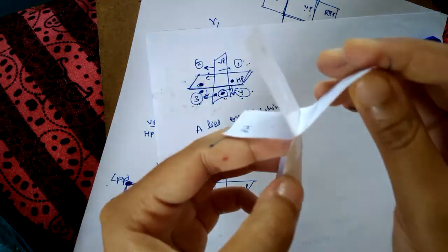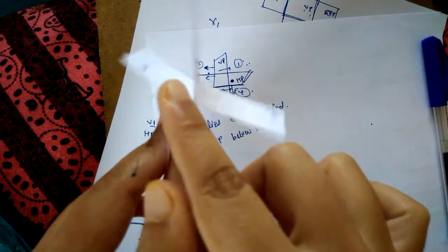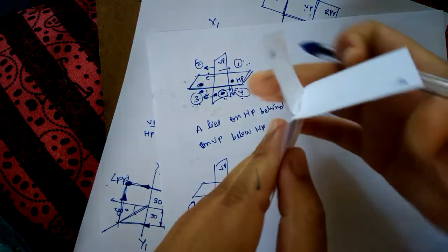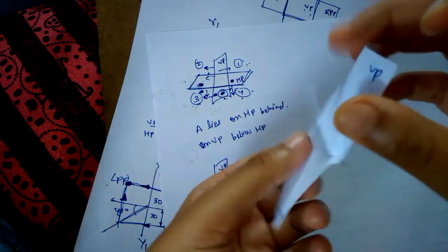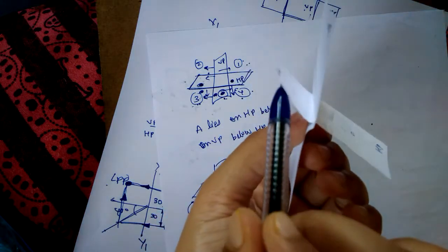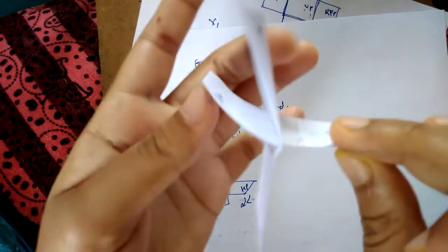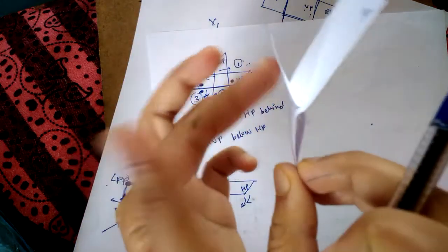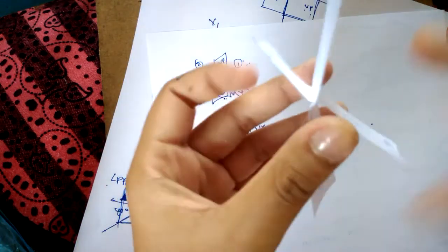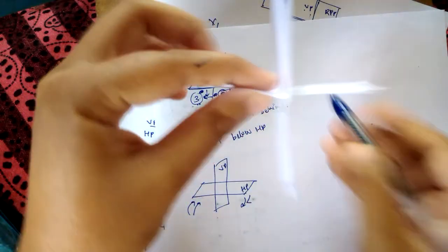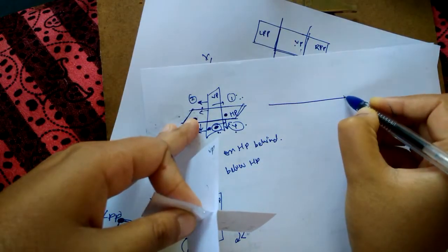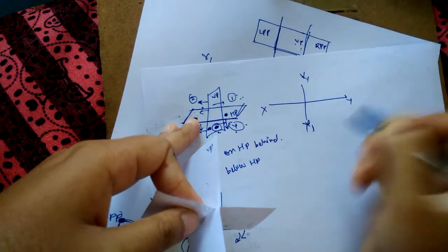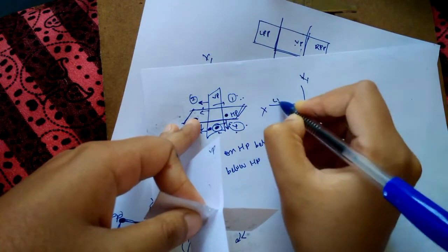But HP and VP coincide below this XY line. And this thing moves upward. The other side of the plane, the third quadrant HP plane moves upward. If you rotate this clockwise, this comes down and merges with this vertical plane. This one moves up and merges with this vertical plane. So what we get for the first angle of projection, when you draw on paper, you draw X, Y, X1, Y1 if required. X1, Y1, VP, HP, LPP.